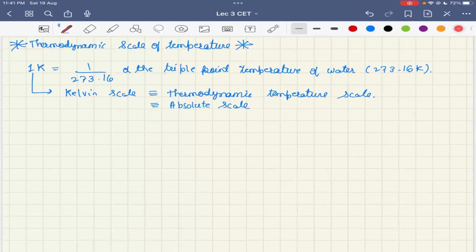Now the second terminology which we are going to study is work, denoted by the symbol W. Work is another mode of transfer of energy. Work is said to be performed if the point of application of force is displaced in the direction of force. It is equal to the force multiplied by the distance, which is nothing but displacement. If F is the force and dl is the displacement of the point of application of force in the direction in which force acts, then work done is given by W, which is the product of F and dl.